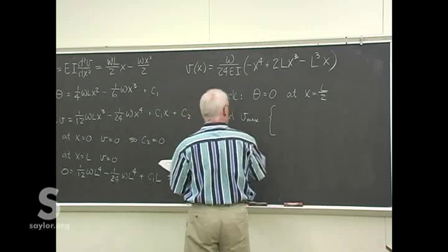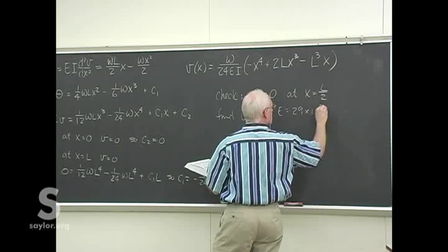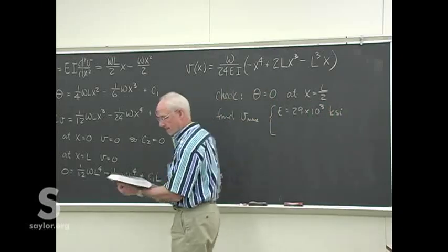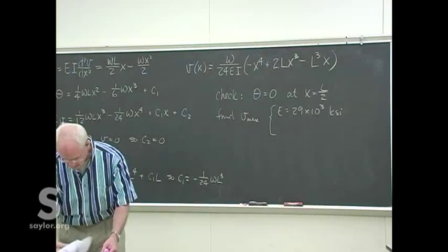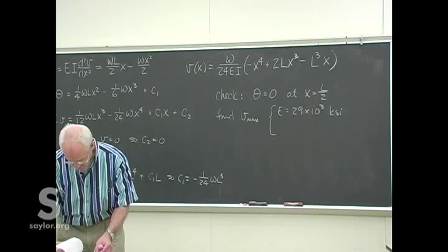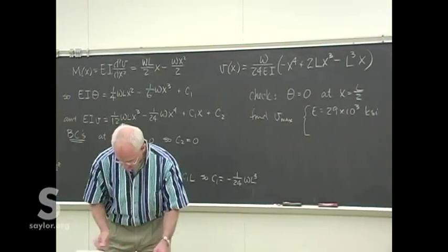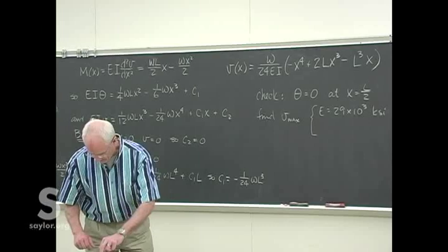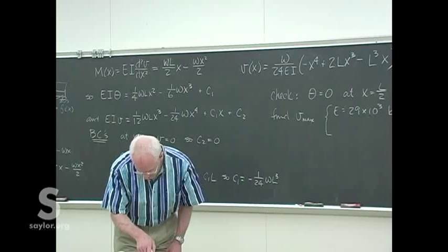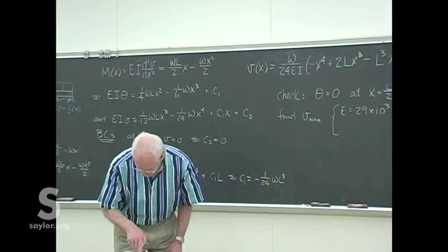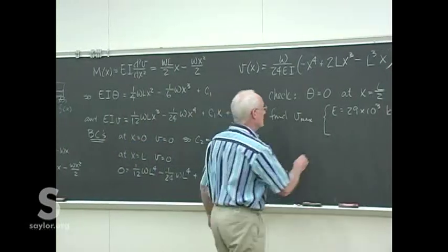All right. So steel in English units. We need E. We'll just call it 29 times 10 to the third KSI. And I'll just pick an H beam out of the table. Where that table is, Appendix B. And we'll figure out just what a Vmax is. So pick a fairly heavy beam here. Let's pick a kind of a little beam, but a heavy beam. So we'll say a W12x87.